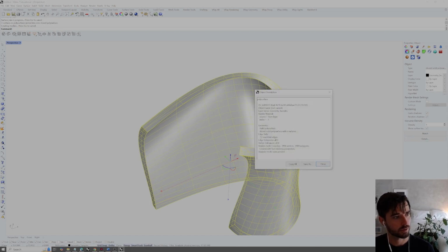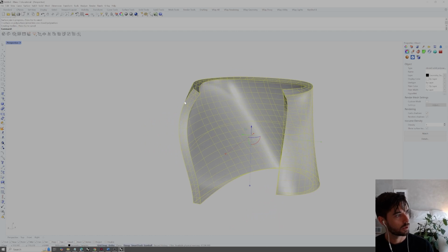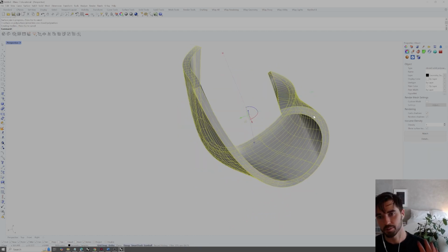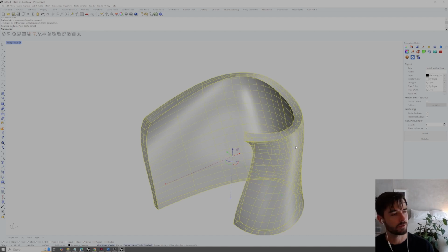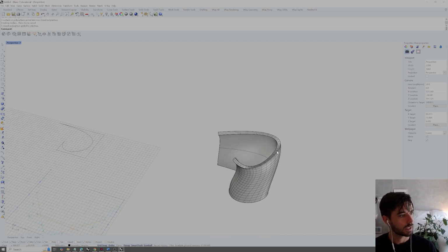So if we go to details, we should also see here closed solid polysurface with 6 surfaces. It's saying 6, not 3, because actually those edges that we lofted are defined by 1 surface on the top, 2 on the sides, and 1 on the bottom. So 4 plus the 2 that we had from the offset open surface, that makes 6. So that's the construct of that solid polysurface.